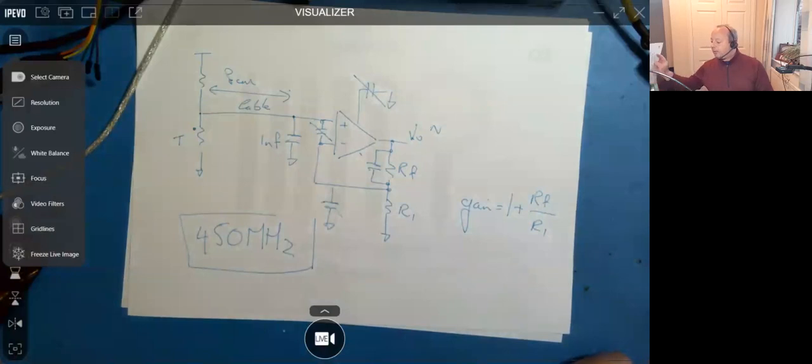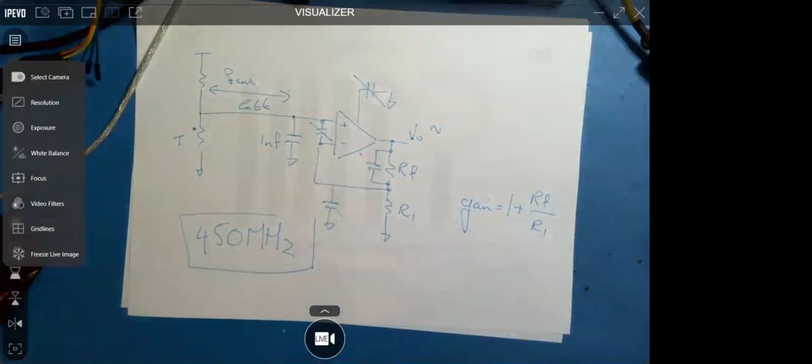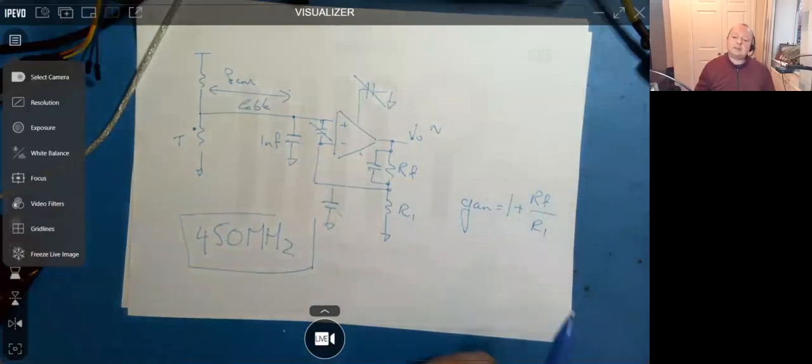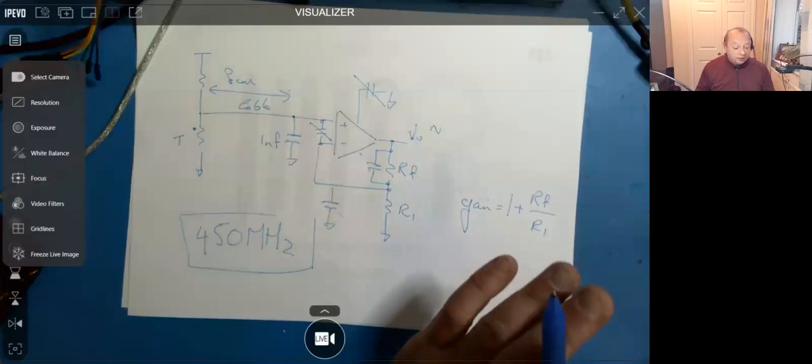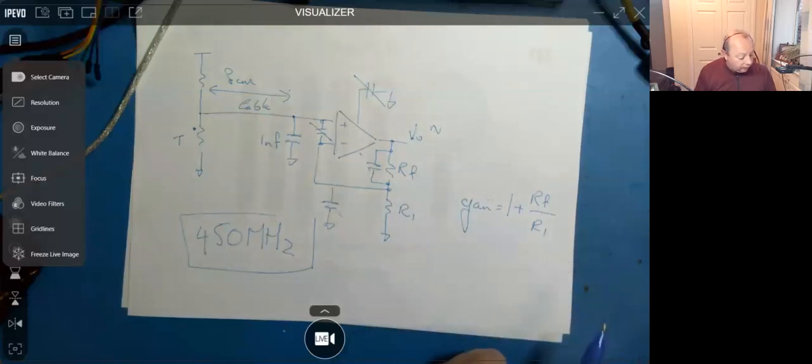So that's what I had for you on that. Can I make a very quick observation? Yeah. I know you've run, but the T is a thermistor, isn't it? Yes, it is. Sorry. Yeah. T could have been used as the feedback resistor, and then you get a nice linear relationship between the resistance of the thermistor. Yeah, I didn't design the electronics as well as using it in the feedback.